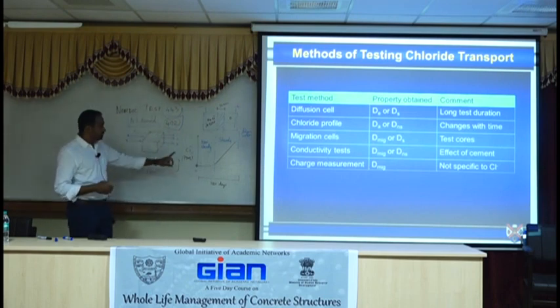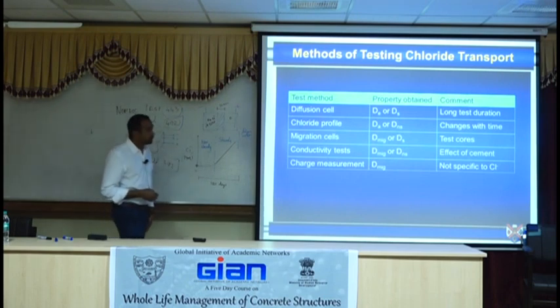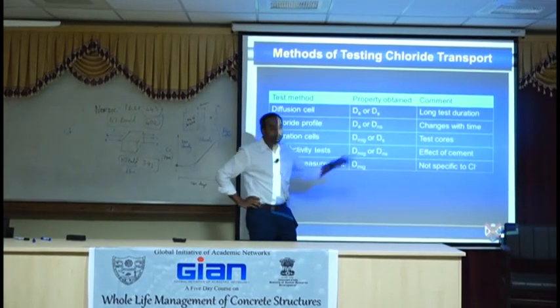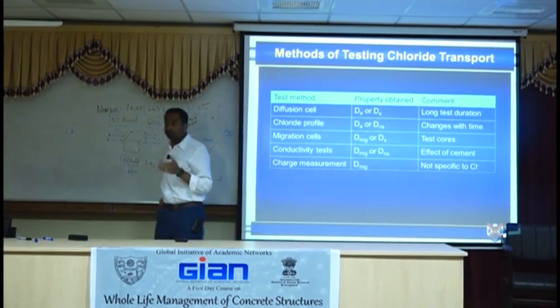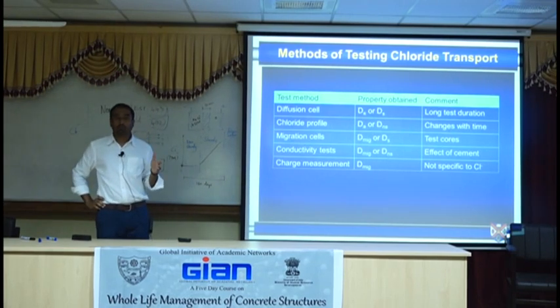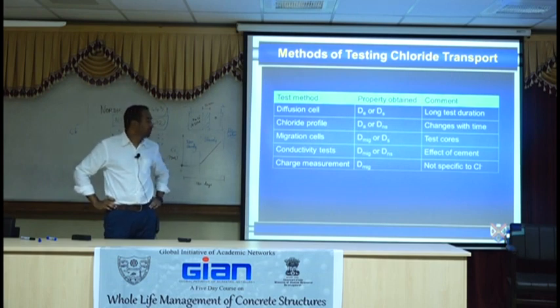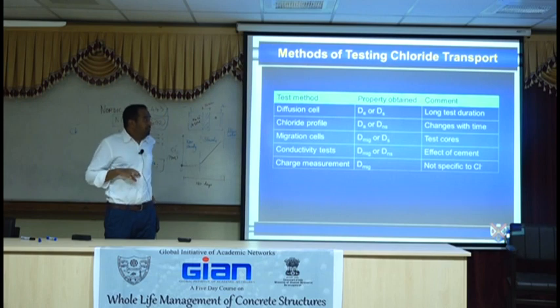It will be a non-steady diffusion coefficient, and it will give you a value in this range. Okay, it's not accelerated, so it's salt water at 0.55 moles, so you have to wait 90 days to get some form of depth. Trick of the trade is, if you're doing testing for others, take 4 cores.